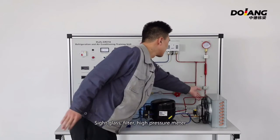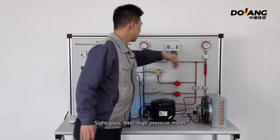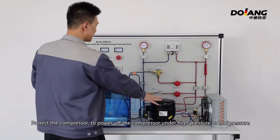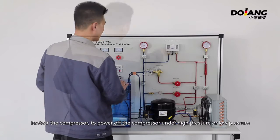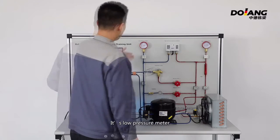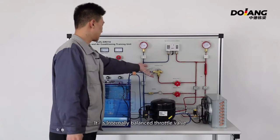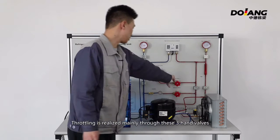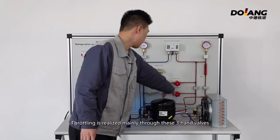Sight glass, filter, high pressure meter, and high and low voltage protector. Its function is to protect the compressor, cutting its power under high pressure or low pressure. This is the low pressure meter. This is an internally balanced throttle valve. Throttling is realized manually through these 3 hand valves.